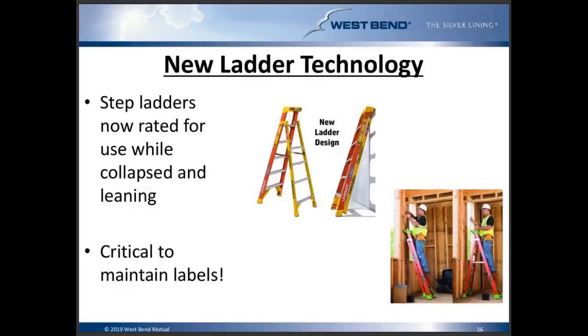So again, I would encourage you to make sure that you have those labels on these and maintain them as best as possible. And typically with these ladders, there are clips that are used in a collapsed position to make sure that they don't extend while using them. Making sure those clips are in good condition, making sure they weren't removed, are all very important. But again, the manufacturer will provide further instruction on how to use these safely and inspect them safely. But these types of ladders, I would definitely encourage your organization to look into, just based on the flexibility of how they can be used.